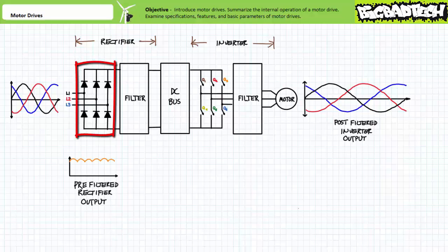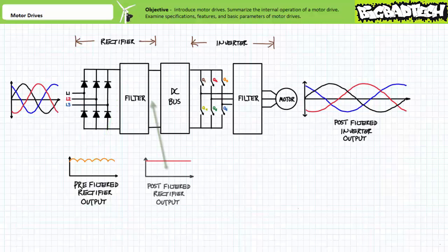Ordinarily, the rectifier is a type of three-phase AC bridge rectifier that produces an output with an inherent ripple. This ripple is removed with a filtration circuit that produces a relatively stable DC value. As mentioned previously, part of the filtration circuit may include energy storage devices like capacitors that can store a lethal charge if not properly dissipated. We'll examine diodes, thyristors, natural commutation, and three-phase bridge rectifiers that make rectification possible in later lectures.